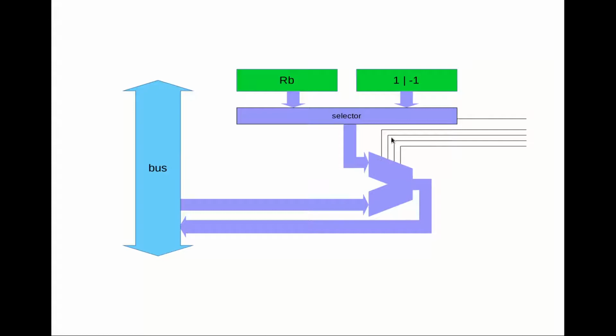And then the ALU operation itself, and since we decided we were also going to implement the nice to have instructions, we're going to need 4 control wires to allow us to designate one of 11 possible operations that the ALU should perform. And then we obviously need the first operand to come in from the bus, and then we need to store the result of that calculation back into that same register. So our output also needs to be connected to the bus.